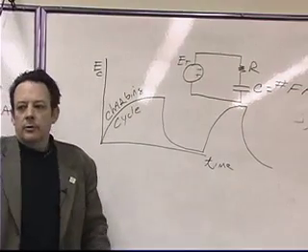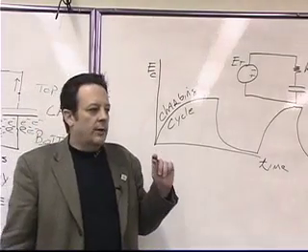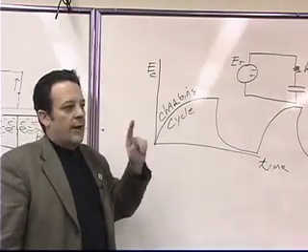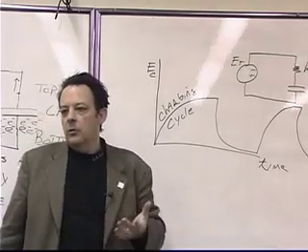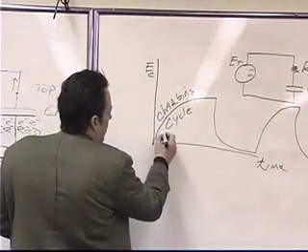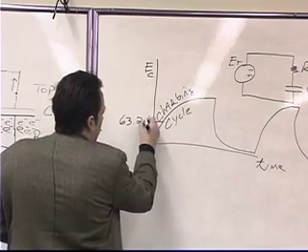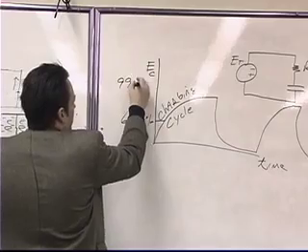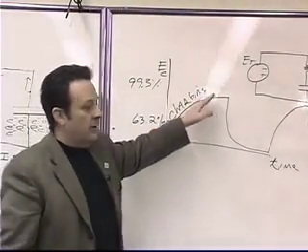Now, you might ask, so what? Who cares? Well, one of the things that is really convenient about this and the fact that it always conforms to the same equation, even though it's an equation that we're not real familiar with, is that we can always predict when the voltage is going to be 63.2%, or 99.3%, or any value between those two.